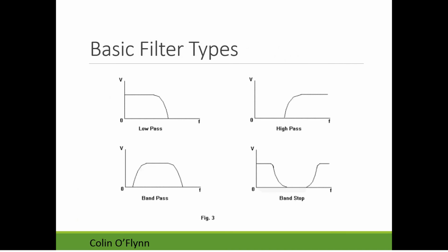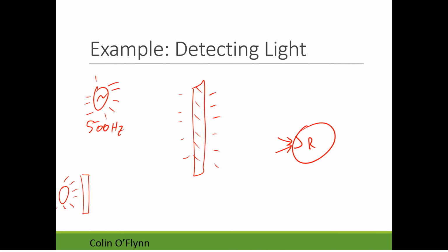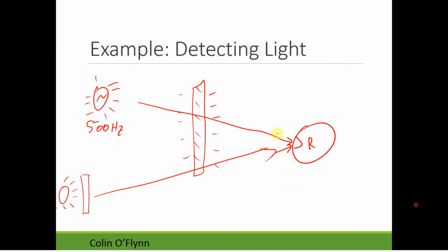This could be a very bright sunny day, and the sun is also going to be entering your robot's field of view. So it's possible that you have these different sources of light all entering into your sensor. And you want to be able to differentiate between that light source that you want to find and all this other stuff. So we can use filters to do that.